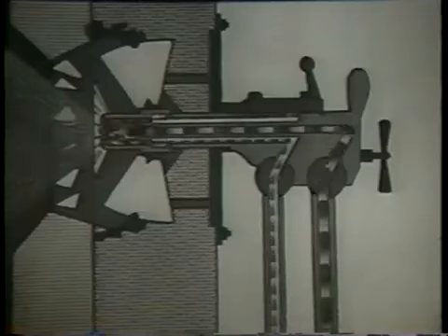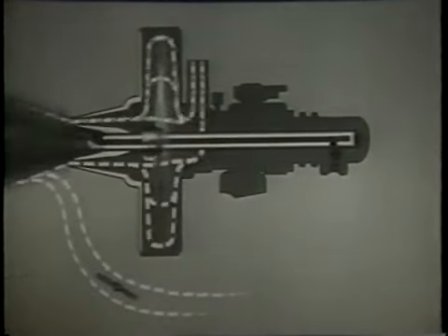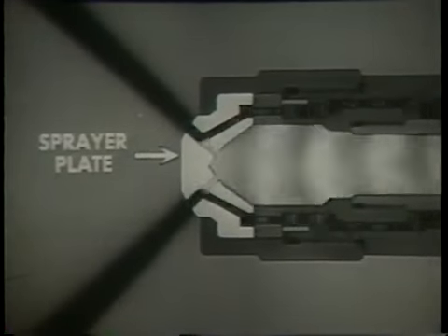In the return flow burner, you vary the pressure on the return oil line to control the amount of oil entering the furnace. In the rotating cup burner, the action of the rotating cup and the air from the blower atomizes the oil. Additional air enters through the damper door. In the steam atomizer, oil under low pressure is heated by the steam passing through the barrel and is atomized at the sprayer plate.